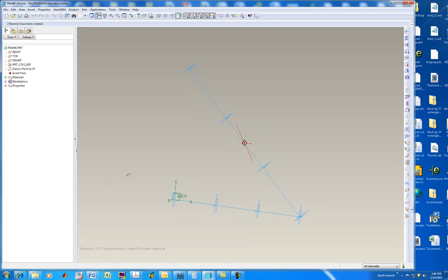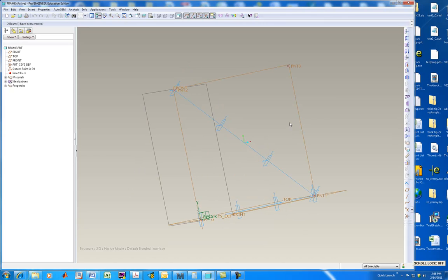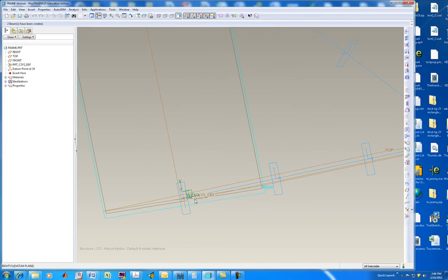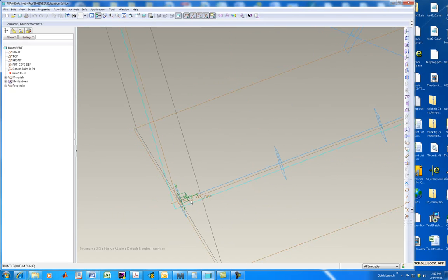Now I need to decide on the kind of loading conditions that I want and the supports that I want. And what I'm going to do is basically make this first end cantilevered, and I'll leave this one like a ball joint. And so I can pre-select point 0, maybe, if I can reach it easy enough.